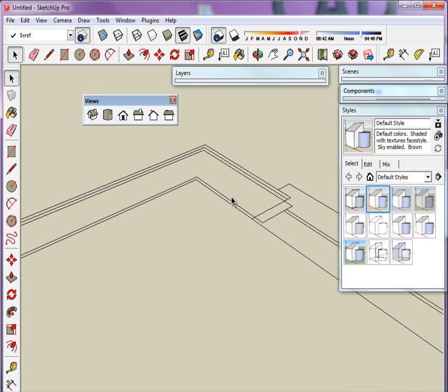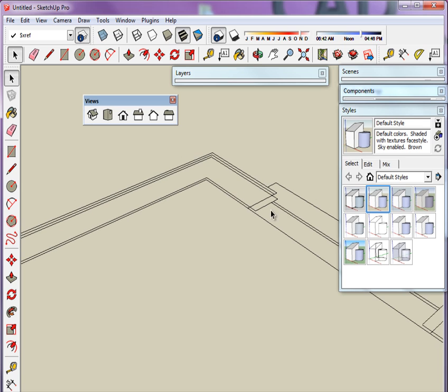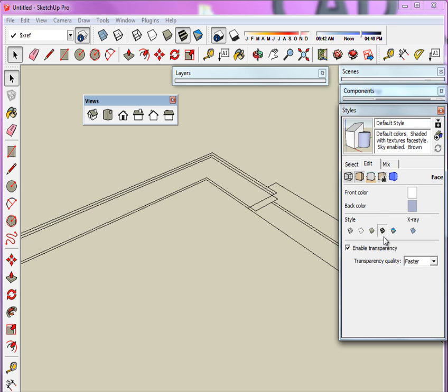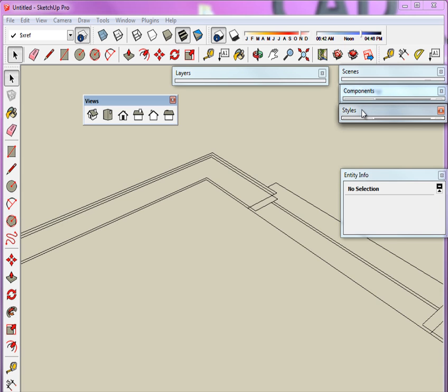No fancy edges. And in most cases, you can look at the edit and check the settings for the face settings. You can see that this is showing textures and shaded with colors. Okay, but you can modify this, and eventually you should have multiple styles for editing the model, for presenting the model, both in color and in black and white, and then fancy and simple styles. So we'll come back to styles later. While you model, keep it simple.